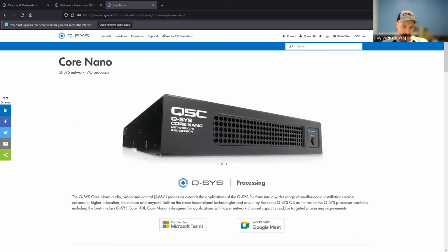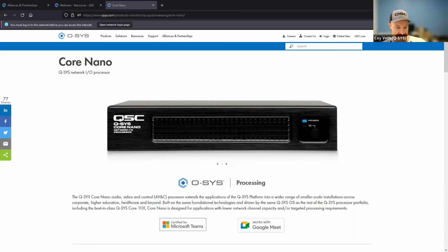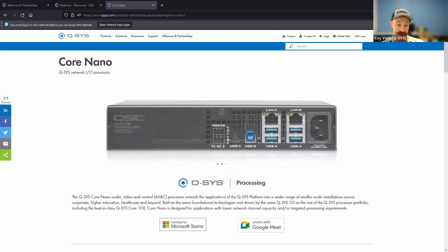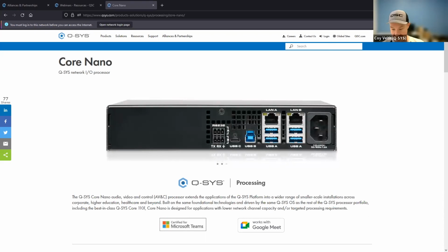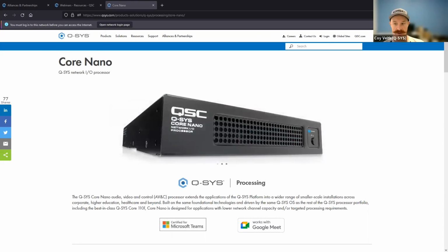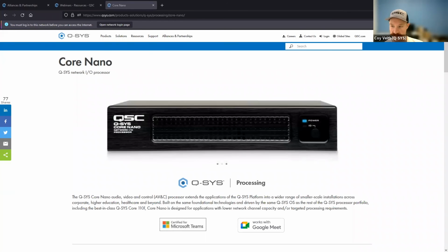Regarding NV32 output to the HDMI on the tab, any sync issues where the tab always thinks the HDMI is active, you can control that within the NV32. You can disable that sync detect. You can turn it on and off, so you actually have full control of that, and it shouldn't be an issue. If you need to resync it, you have the ability to force that if you want. So there shouldn't be any issues there.